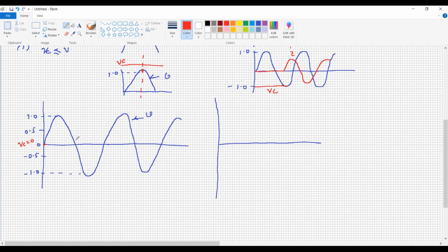Now, when we switch on the capacitor, during this condition, it will produce a transient current, and this transient current will have more oscillations in the positive half cycle as well as the negative half cycle, and somewhere it is going to settle. So this is the current which is going to flow into the circuit.